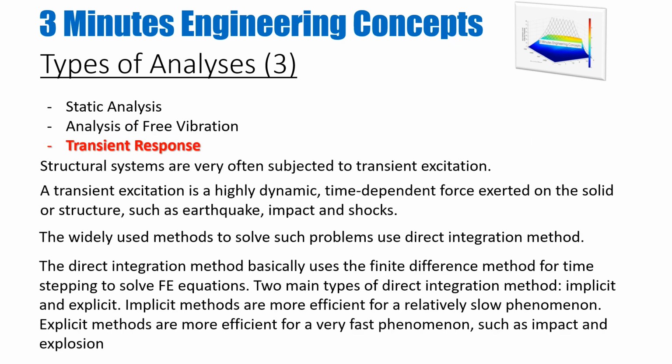The last but the most difficult one is transient response. In this case, our structures are often subjected to transient excitation. As I told you, your load is changing with time. It's a highly dynamic problem, for example earthquake, impact, shocks, etc. In such cases, you need to use different approaches, because you have two functions now. You're solving for displacements and you're solving for time as well.